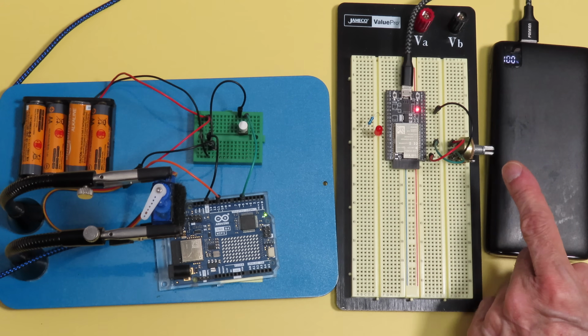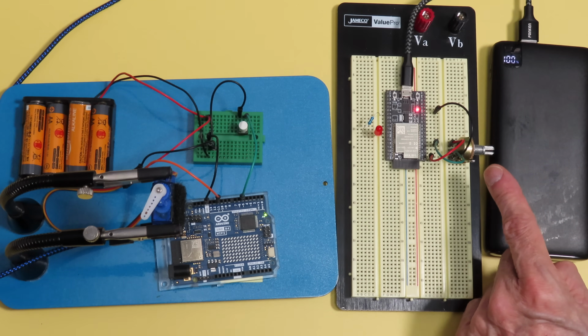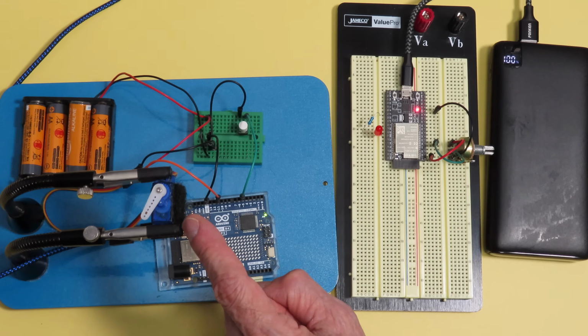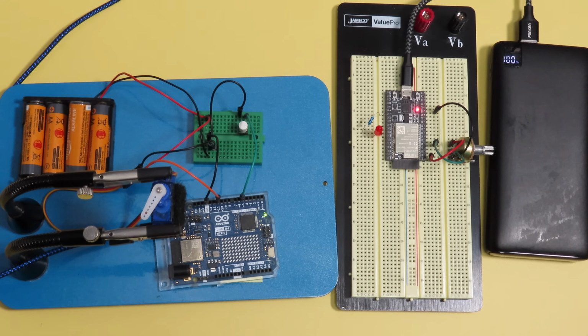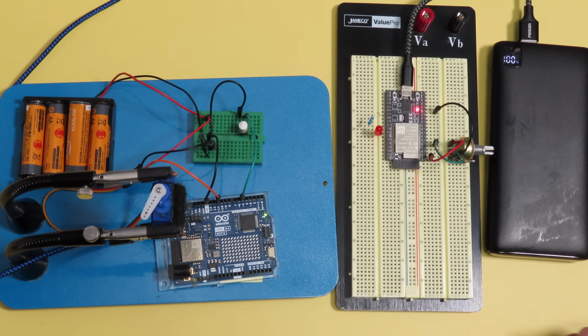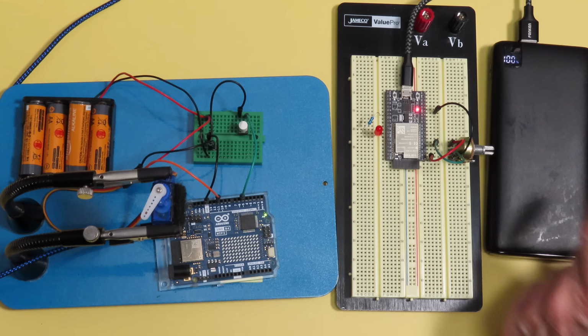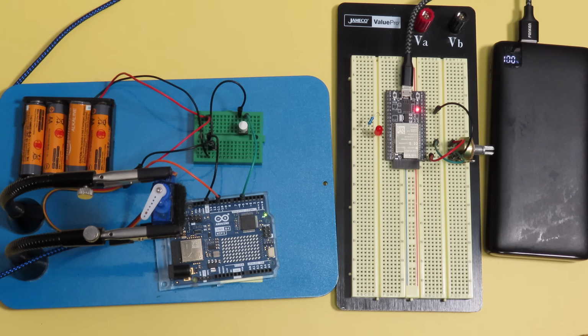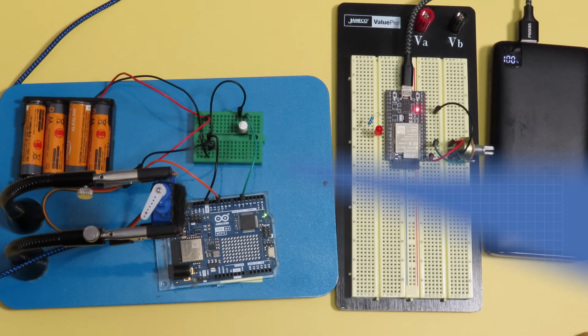However, the pot is giving you a value of 0 to 4095, and we need a value of 0 to 180 for the servo. So what you would need to do is modify the ESP32 code and add a map function into it to map that down to 0 to 180, and then synchronize the two variables. So give that a shot. You should be able to control your servo motor with the potentiometer on the other device, proving out the cloud-to-cloud variable synchronization in the Arduino IoT Cloud.